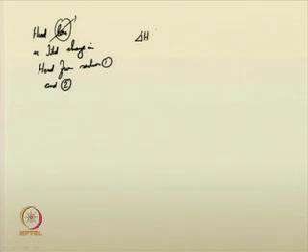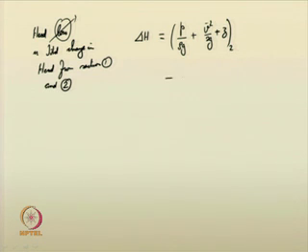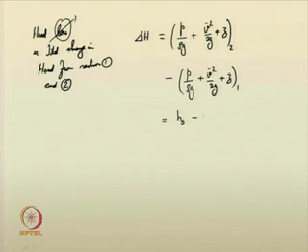We can write it as the total change in head from section 1 to section 2, that is del H. This is equal to the total head at section 2 minus the total head at section 1, and this is nothing but equal to HS minus HF, where HS is called the pump head, the additional energy head you are going to supply through the pump.